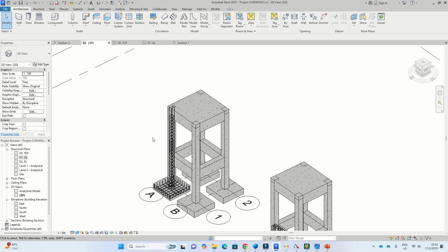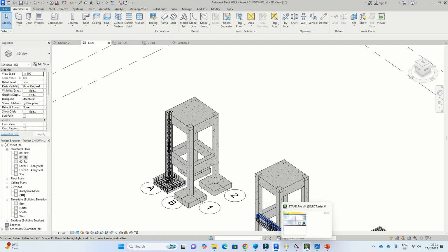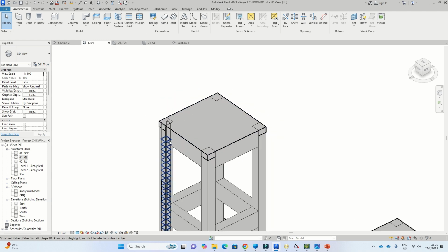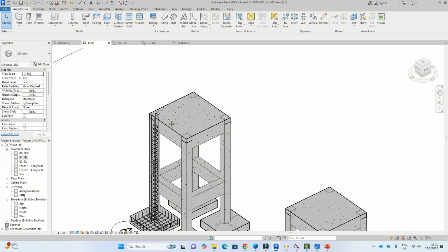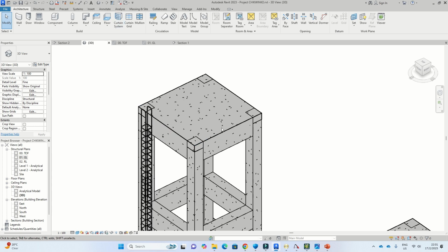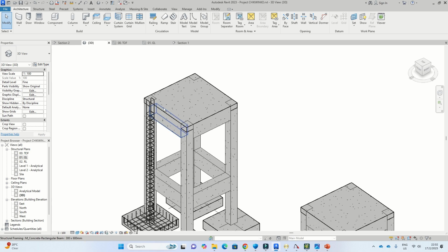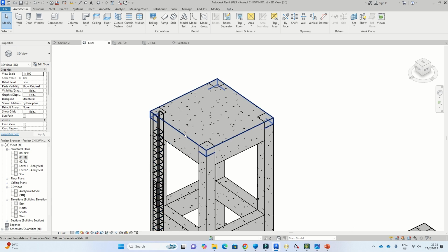So if we choose to design this beam here, from this point to this point, you can see that it's 2 meters. This is not going to be a UDL, the load that is going to apply on this beam, because there is a law for beams that says load goes to the nearest support. So it is in this slide that you find out that the load for this one is going to be triangular when it goes into this beam.